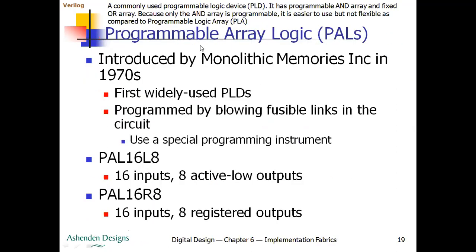For your syllabus, we have PAL 16L8, which has 16 input lines and 8 active low outputs, hence the name PAL 16L8. The next version of it is PAL 16R8. PAL stands for programmable array logic, and these are commonly used programmable devices which have a programmable AND array and a fixed OR array. Remember this point.